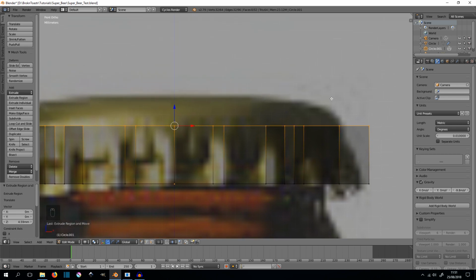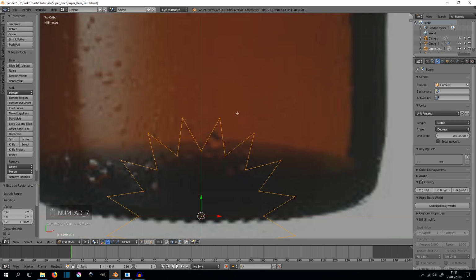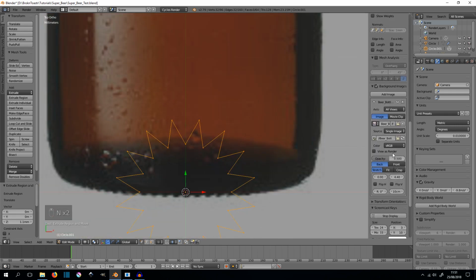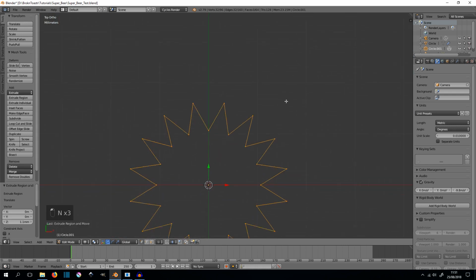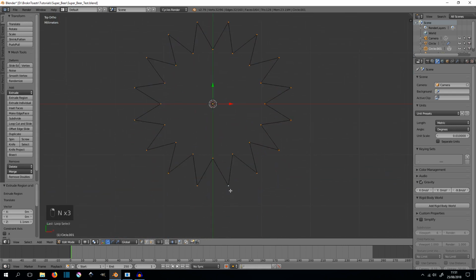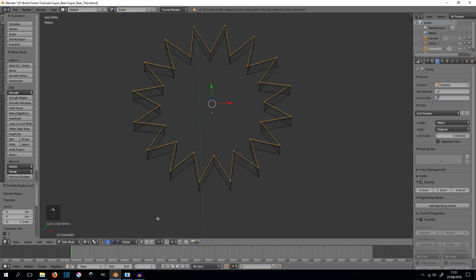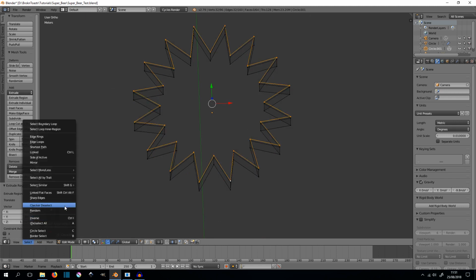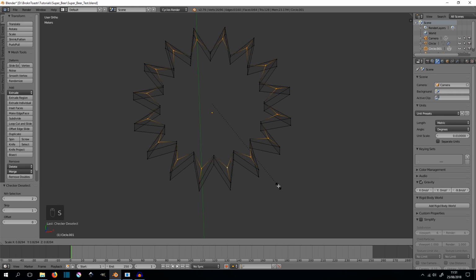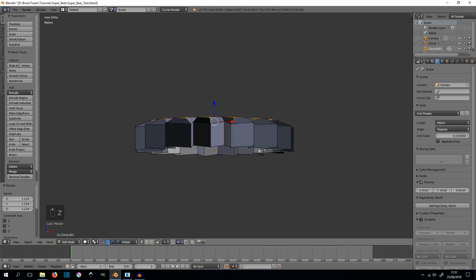Then I'm going to extrude it once more in a very small displacement. I will press 7 so I get a top view. I forget about this image. I will repeat the process of check or deselecting, and we will make this shape return to a circle shape. It only has to be approximately the same. It doesn't have to be exactly equal.